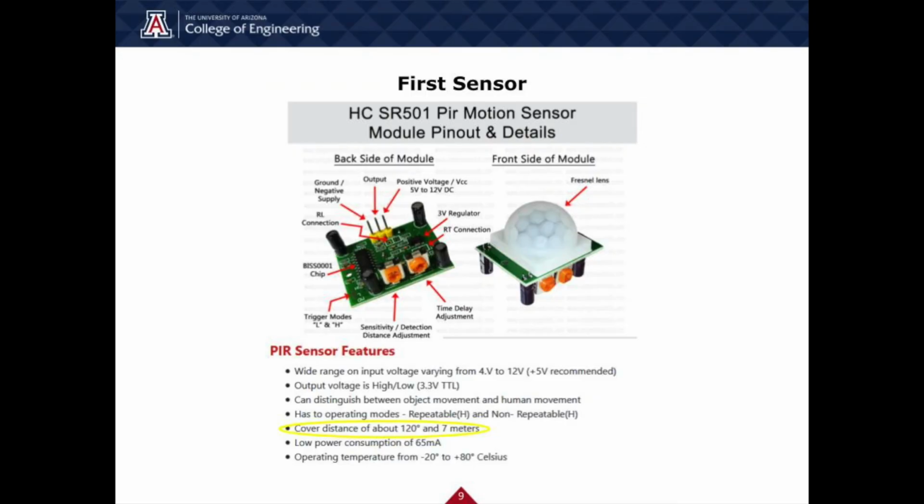The first PIR sensor we selected was HCSR501 and showed problems in early testing. The PIR sensor was believed to have adjustable distances between 1 to 21 feet, but the sensor did not pass testing, leading us to reanalyze our options.